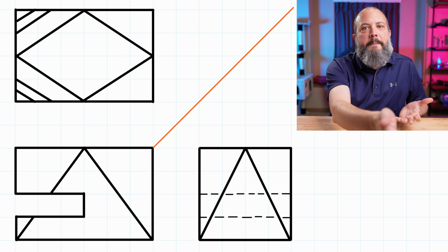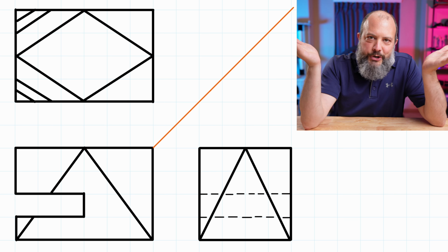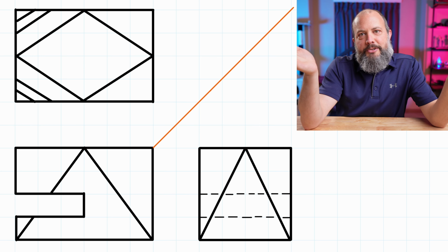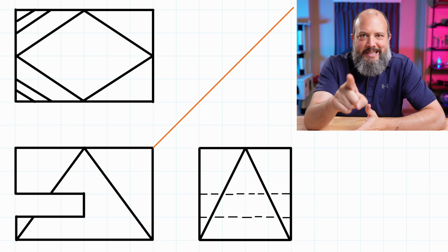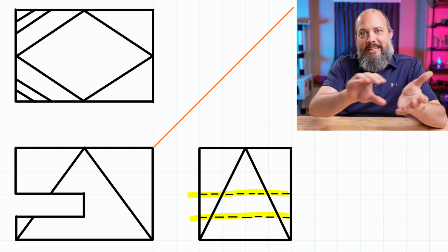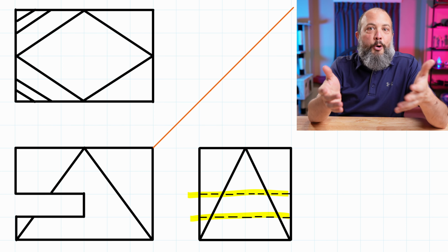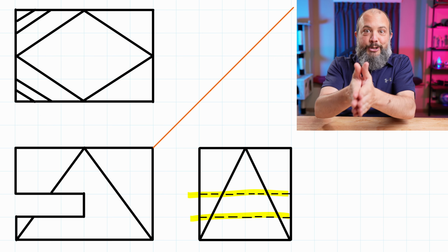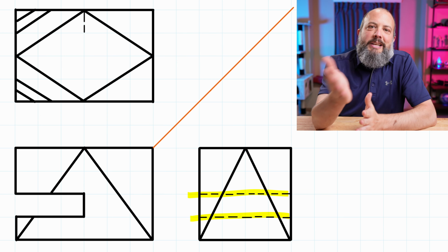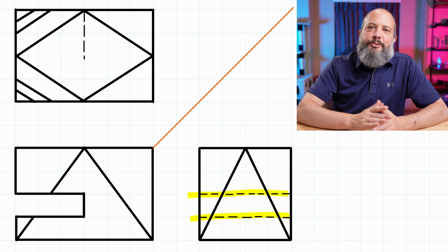surface further back. And with all of that, you would think surely this problem is done, but sometimes your professors are just out to get you. So of course there's one other missing line. And if you look over on the right side view, right, there's dashed lines that go all the way across to represent the hole that's hidden, because right in the center of the part, that's where the edge of the rectangular hole is. So there needs to be a hidden line right slice through the middle of the part.